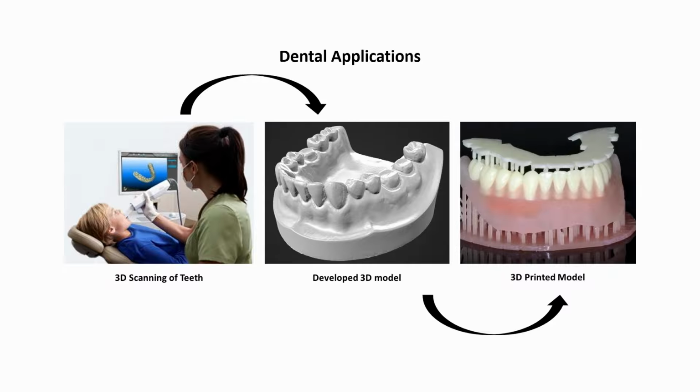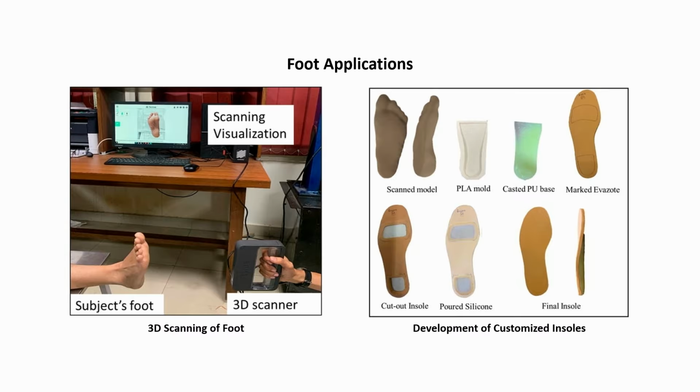If you are able to move the scanner around stably for a while, you will see the entire 3D foot model show up on the screen of your computer, which you can rotate, pan, zoom, or do anything with, right. This makes life very easy, where your entire foot model can be traced within maybe 15 to 20 minutes. And there are places where you will see the model is not developed, there are some vacant spots and cavities. That is where you can move your scanner around a little bit more, and it will scan that part as well and complete the model, right.